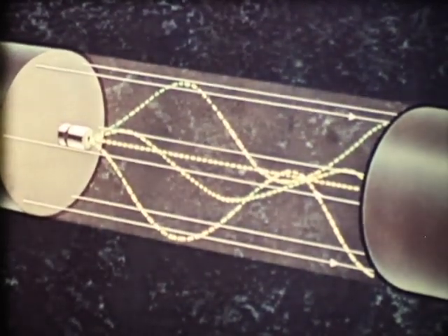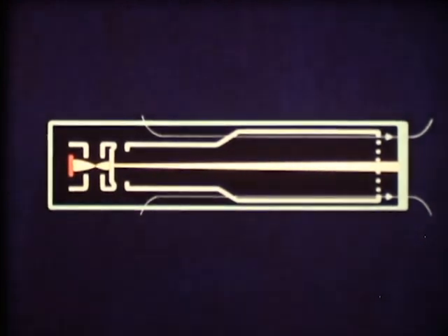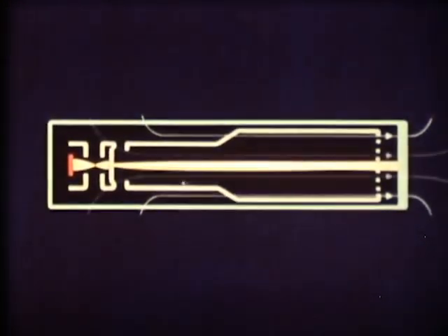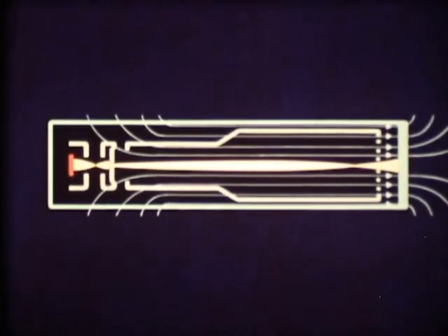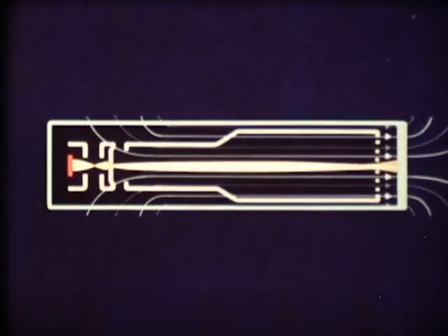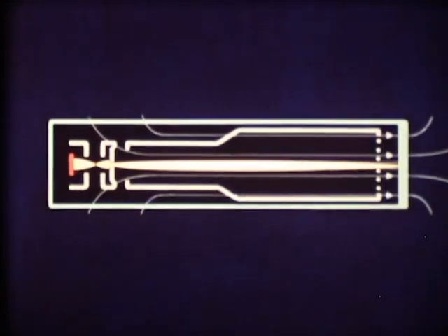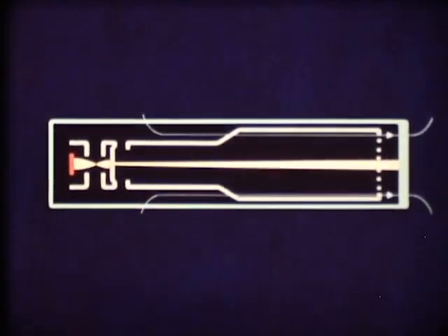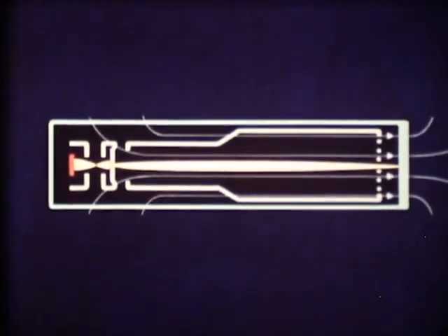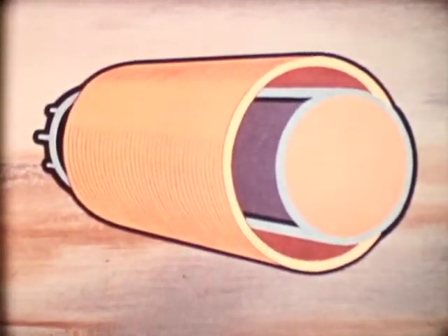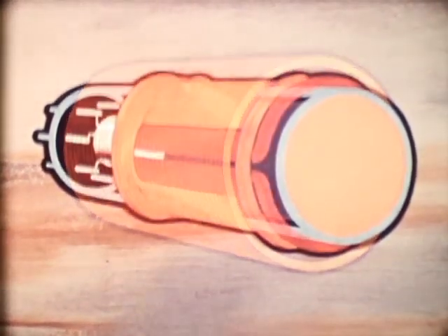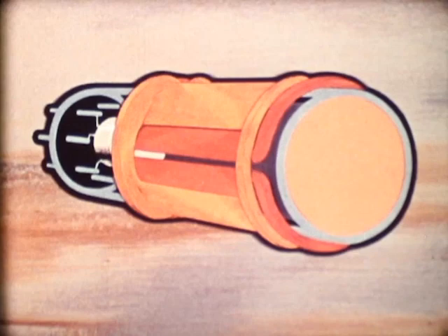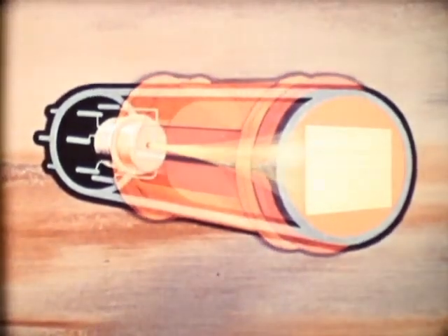The stronger the magnetic field, the stronger will be the focusing effect. But for optimum focusing, the field strength should be such that the focal point occurs exactly at the signal plate, and this is achieved by controlling the current flowing in the focusing coil. Another coil assembly comprising deflection coils provides the scanning motion.